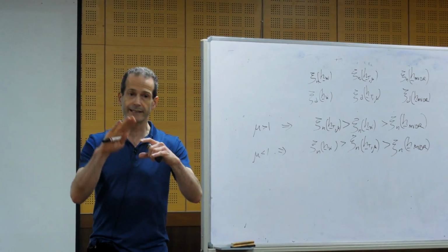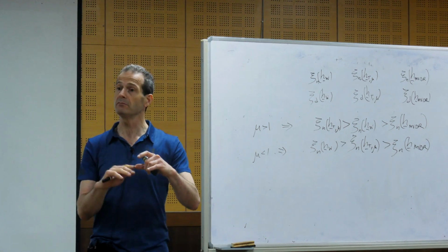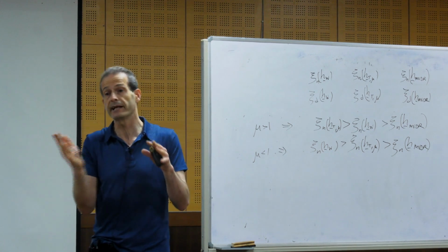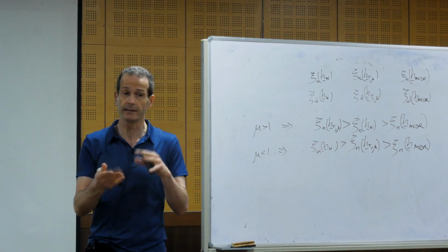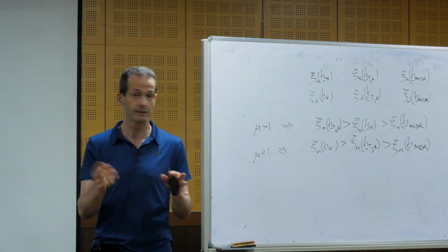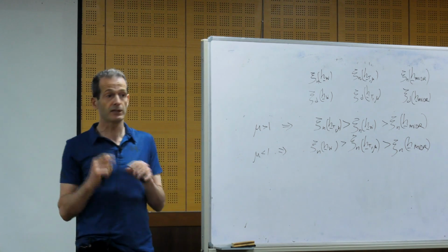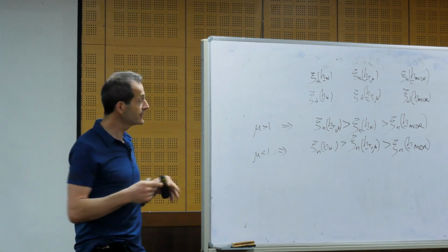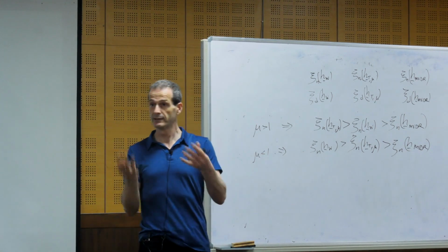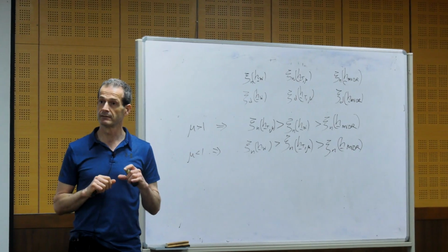It will also decrease some noise, but introduce some distortion based on the signal-to-noise ratio. It depends if we have more signal or more noise, because it tries to minimize the mean squared error. The trade-off is very similar to the Wiener filter. It just gives different weight with a parameter mu to the noise, to the signal-to-noise ratio in that signal subspace.